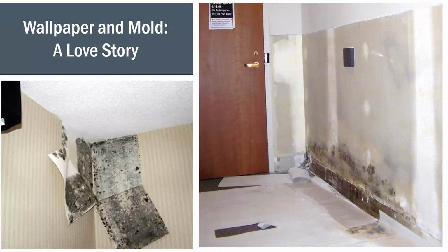Because if you pull that wallpaper away, all you're doing is potentially making all of that suspect mold airborne. And that looks, I mean, that looks nasty. At least when it's behind the wallpaper, it's somewhat contained, it's somewhat encapsulated. But I would caution anybody trying to investigate that any further. I would just leave it at, we know there's an issue, get some professionals in to take some readings and go from there.